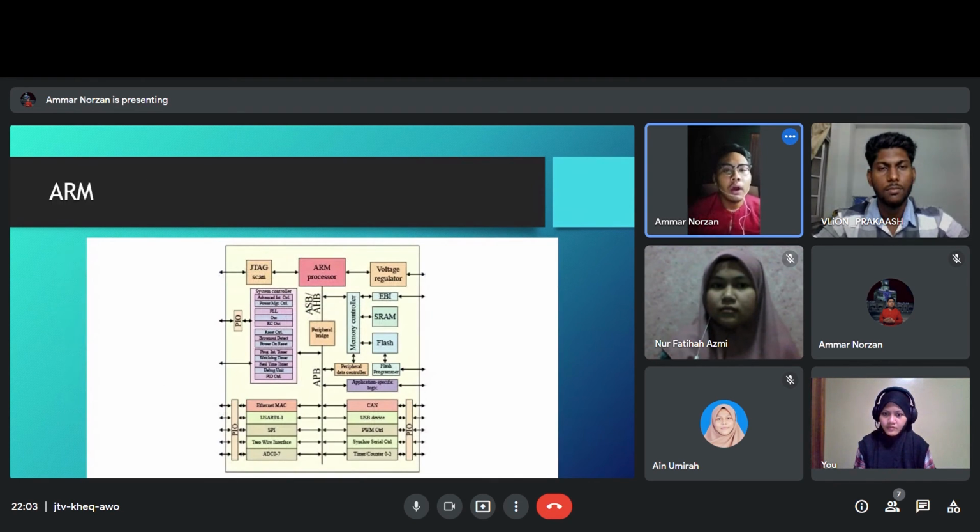So for ARM architecture, it consists of a 32-bit ALU, or arithmetic logic unit, with several 32-bit general purpose registers and status registers. The loop shift of n bits and the arithmetic shift of n bits to the right can be completed at one time. Therefore, in order to improve the operation speed, ARM adopts the method of two-digit multiplication to realize the operation of adding one shift according to the 2 bits of the multiplier.